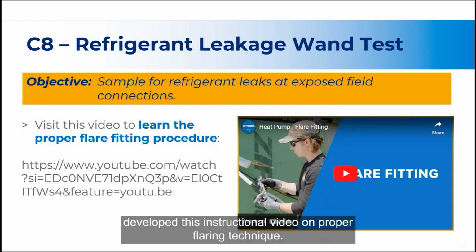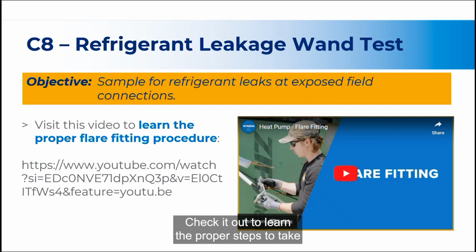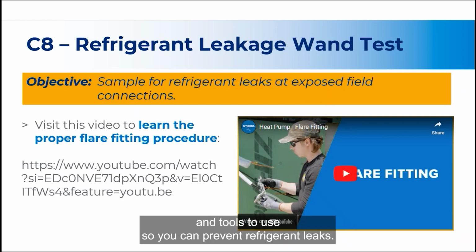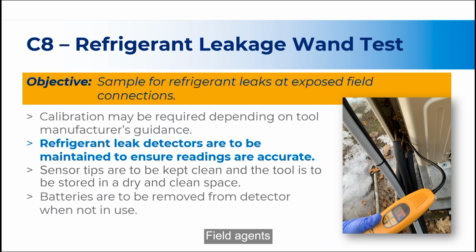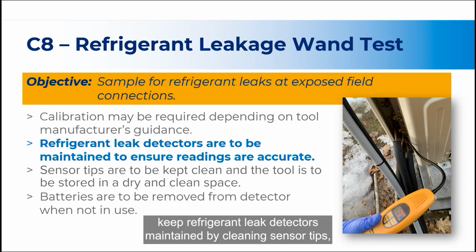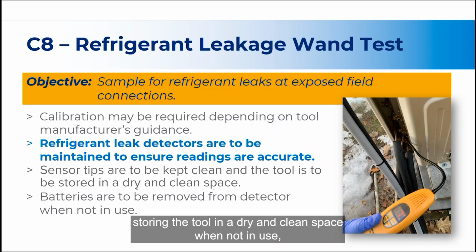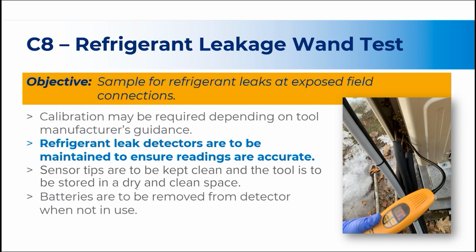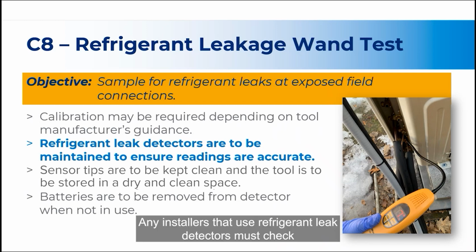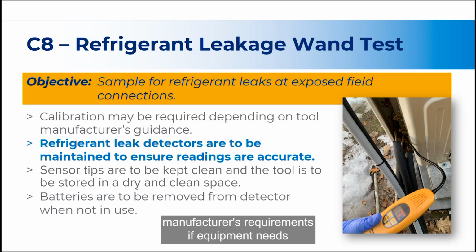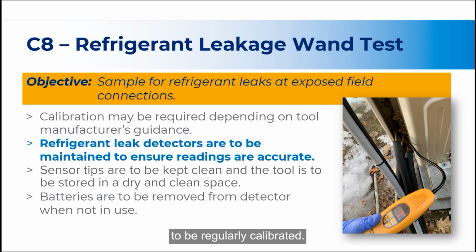NYSERDA Clean Heat Connect developed this instructional video on proper flaring technique. Check it out to learn the proper steps to take and tools to use so you can prevent refrigerant leaks. Field agents keep refrigerant leak detectors maintained by cleaning sensor tips, storing the tool in a dry and clean space when not in use, and removing batteries when not in use per the manufacturer's instructions. Any installers that use refrigerant leak detectors must check manufacturer's requirements if equipment needs to be regularly calibrated.